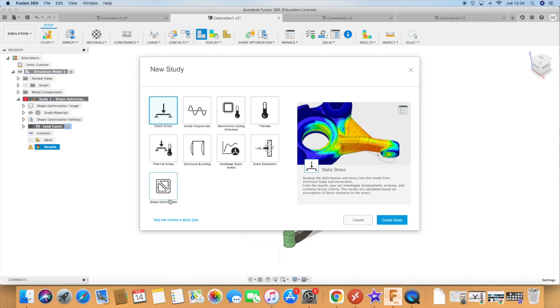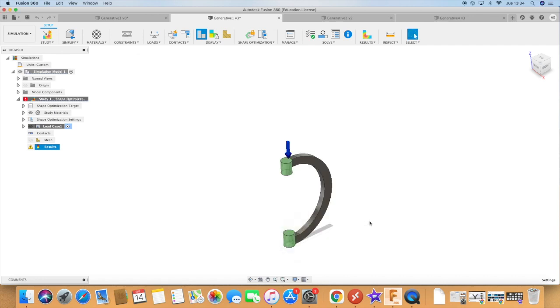Anyways, I'm gonna cancel this one because we don't really need that for now. So as usual, what I've done in here is I've chosen in green those regions, which are gonna be my preserved regions because I still want to keep them once the simulation is done. Then using my constraints and loads, I made the bottom surface of the cylinder fixed. This guy, I'm just applying a force.